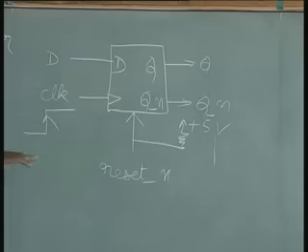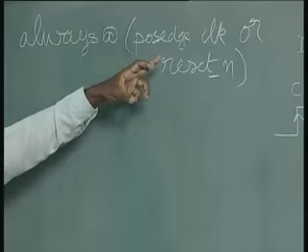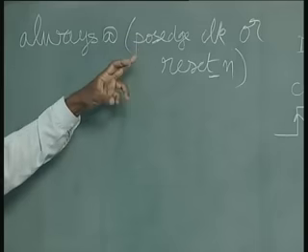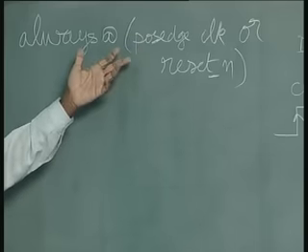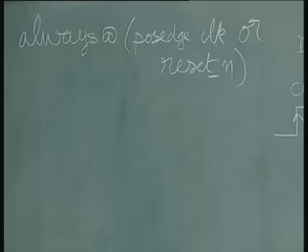That is the reason why, in industry especially, this is a very important signal, and has to be given due care. And so is the case with clock. Although negative edge clock also will work, somehow positive edge seems to be more popular, because that happens to be the first thing to arrive compared to the negative edge in such a clock.